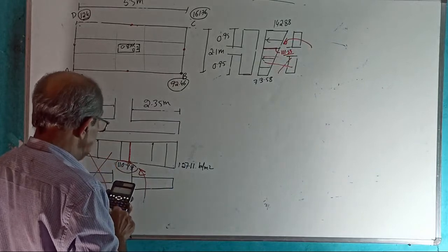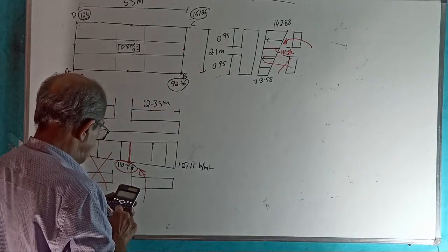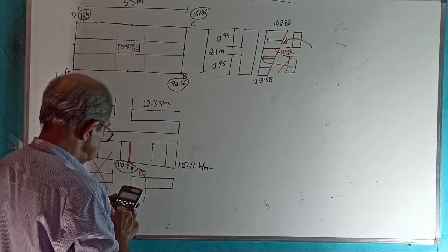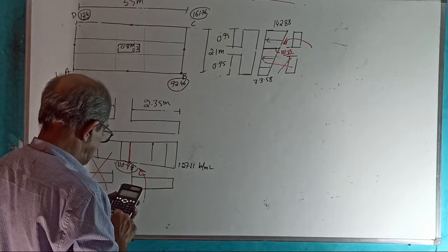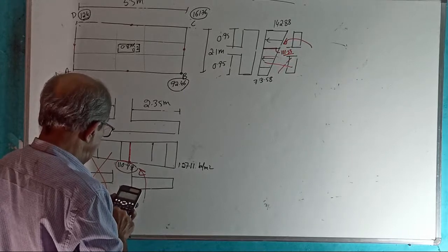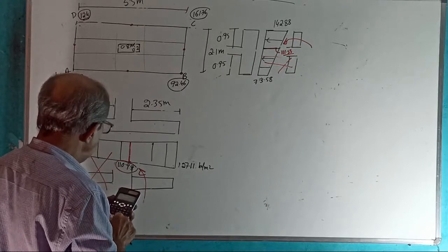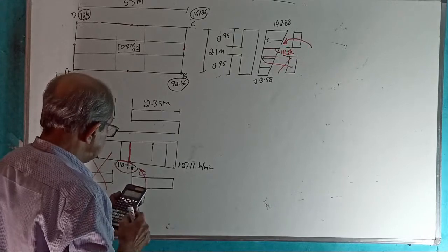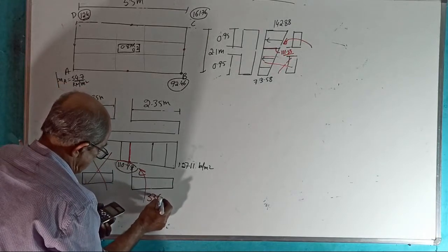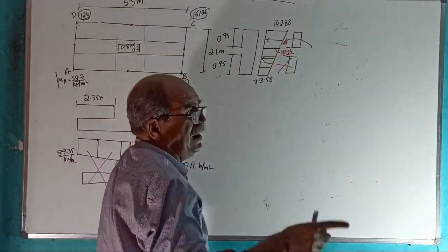110.98 plus twice of 127.11 divided by 110.98 plus 127.11, into 2.35 divided by 3 is the distance 1.2, correct, multiplied by 110.98 plus 127.11 close, divided by 2 into 2.35. This bending moment is 336.14, and this is the maximum BM for lengthwise bending.